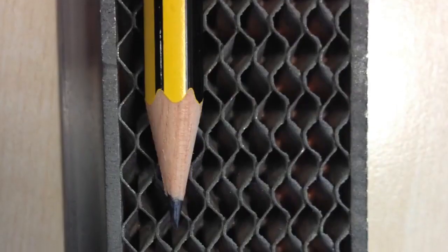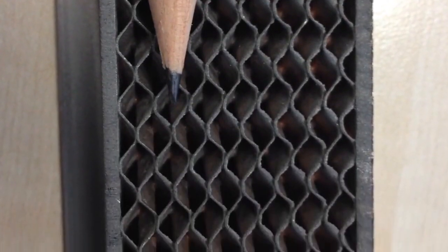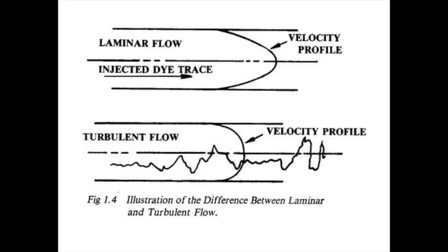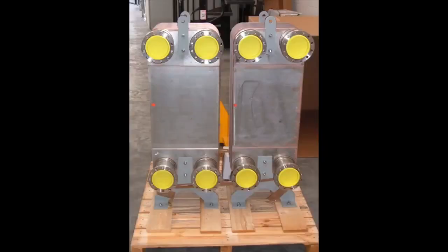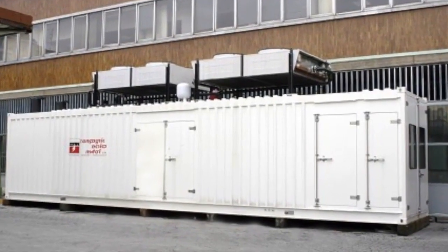Plate heat exchangers enable working with narrow logarithmic mean temperature differences due to their significant advantages, as we have previously explained, of operating in perfect countercurrent and having a highly turbulent flow that enhances their heat transfer coefficients. For a shell and tube heat exchanger, the average temperature difference must be slightly larger. Otherwise, we have high exchange surfaces due to lower coefficients compared to a plate heat exchanger. If we even talk about finned coil exchangers, therefore air-water or air-steam exchange, this average dt tends to widen even more.